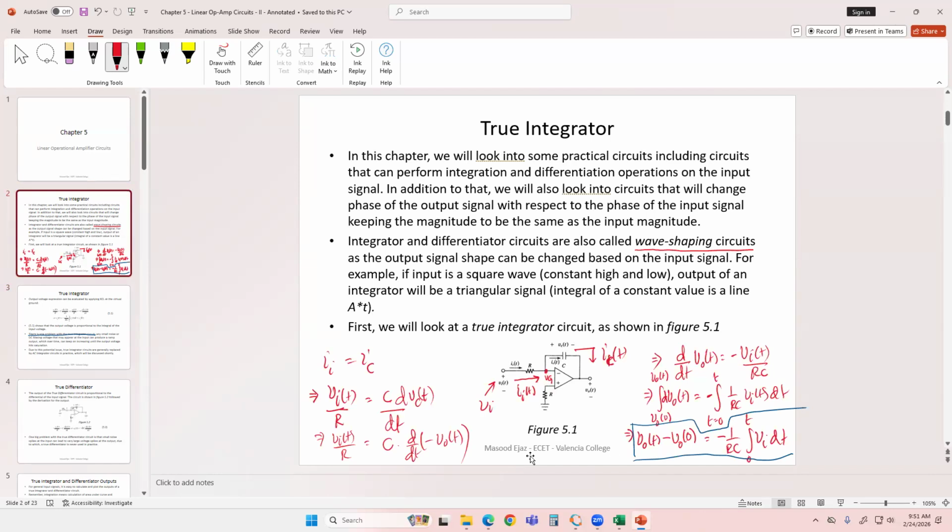But in addition to the input signal, or even if you don't have any input signal, let's say the input signal is 0, but somehow you have a stray noise, or you have DC biasing current because of the biasing of the operational amplifier, a DC biasing current that is going constantly inside your inverting input.